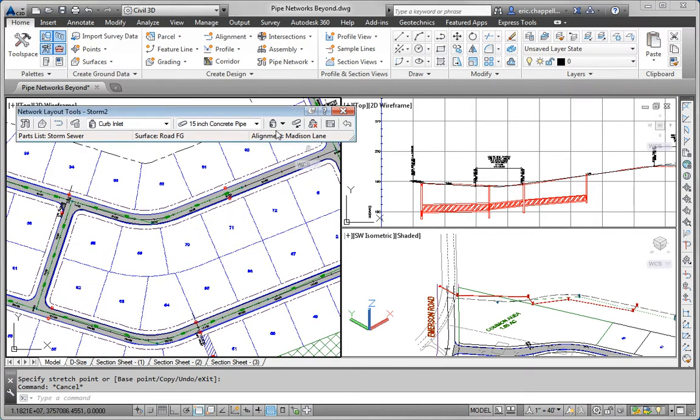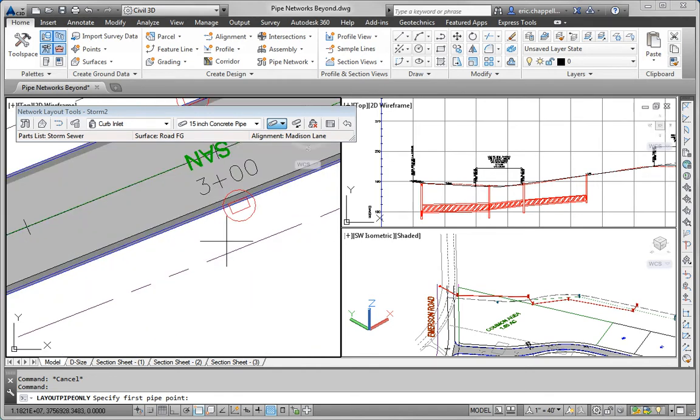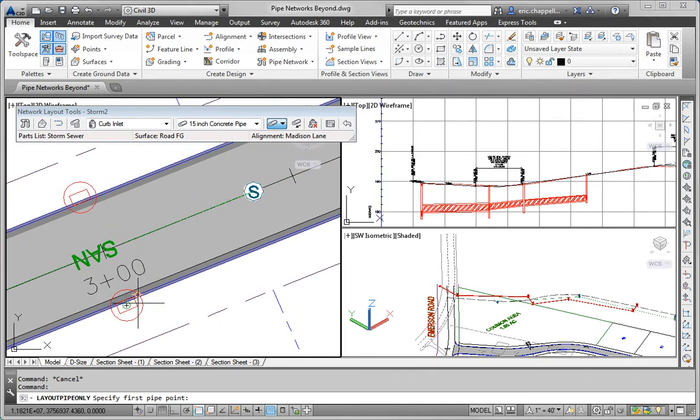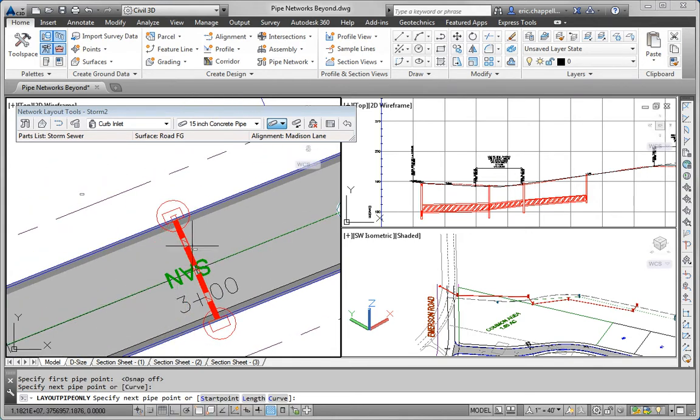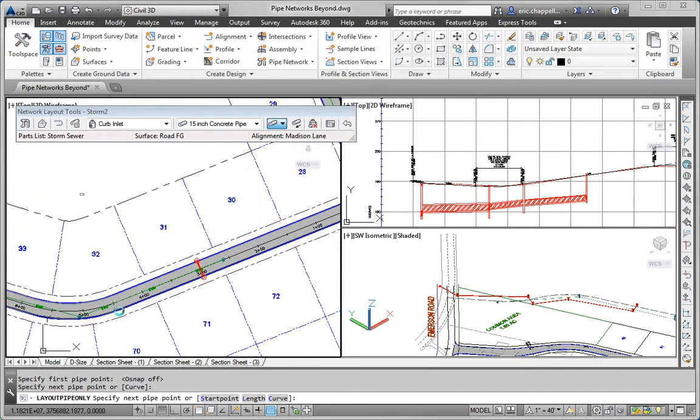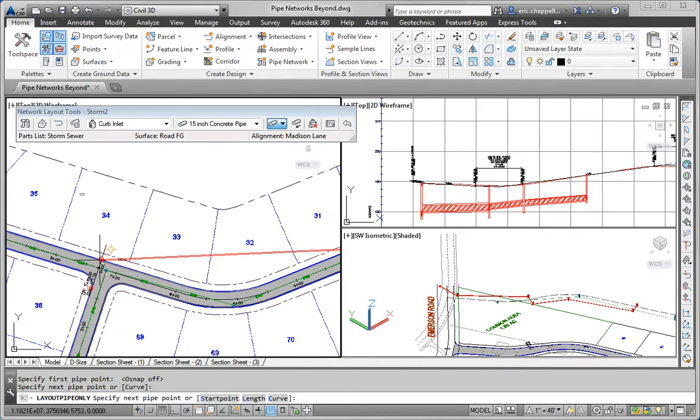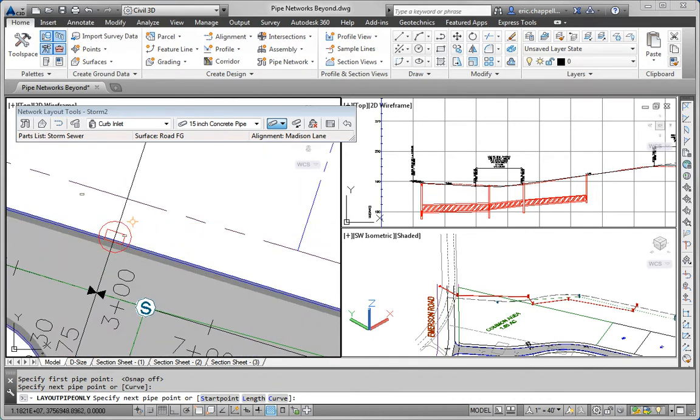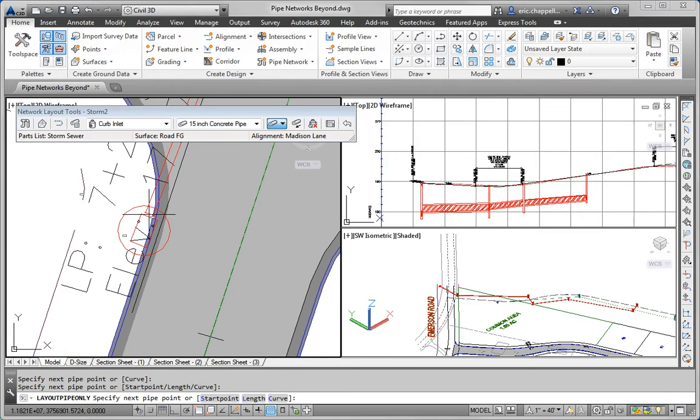Now one thing I learned to be careful about is to make sure that I'm getting the right feedback as I'm creating the pipes. And here's what I'm talking about. I'm going to zoom in nice and close and make sure that I'm seeing the glyph here. In fact, I'm going to turn off my O-snaps and make sure I see that little yellow glyph that indicates that I'm connecting to the structures. And a visual indicator that I've connected is I actually see the pipe get cleaned up. It appears like it's been trimmed at that rectangle. So watch for that. Here's a spot where I know I'm going to need a manhole because I'm cutting right through the middle of lots 32 and 33, but I'll take care of that later.